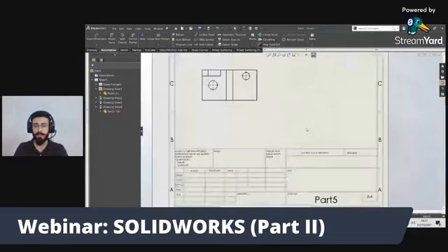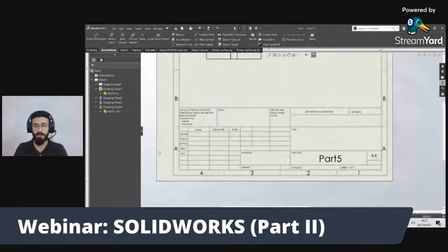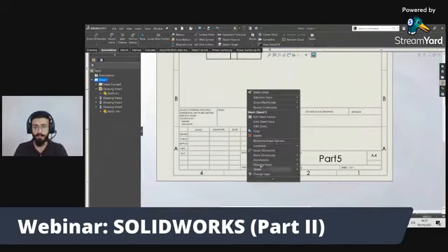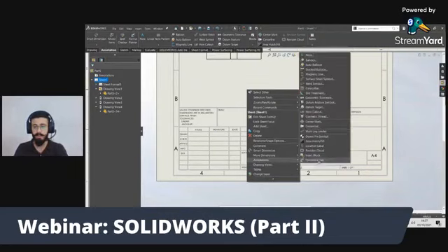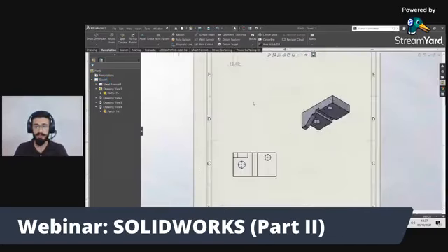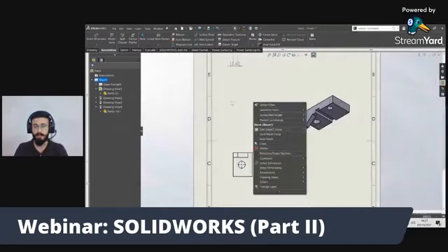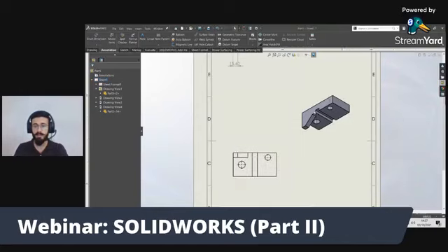And the next and important part is how to make alterations in this. Just click here. There is an option, tables. There is an option, annotation. From there you can add text here, you can insert a box here, everything. But if you want to edit your sheet, just right click on it.